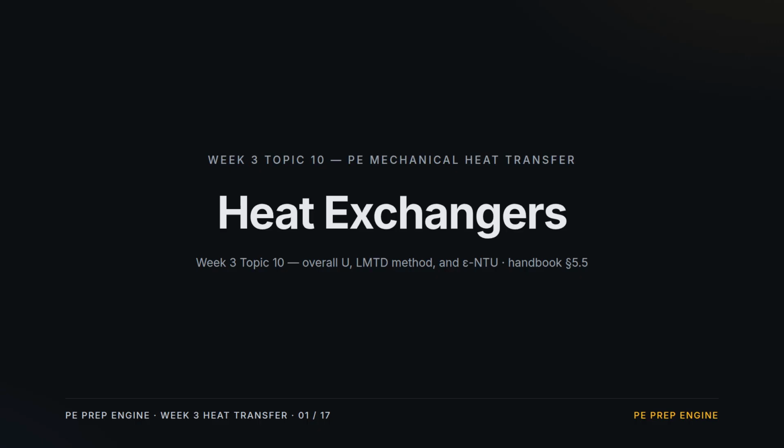Topic 10 of Week 3, Heat Exchangers. The overall coefficient U that bundles both fluid films and the wall into one number. The log mean temperature difference method for sizing, and the effectiveness NTU method for when an outlet is unknown.